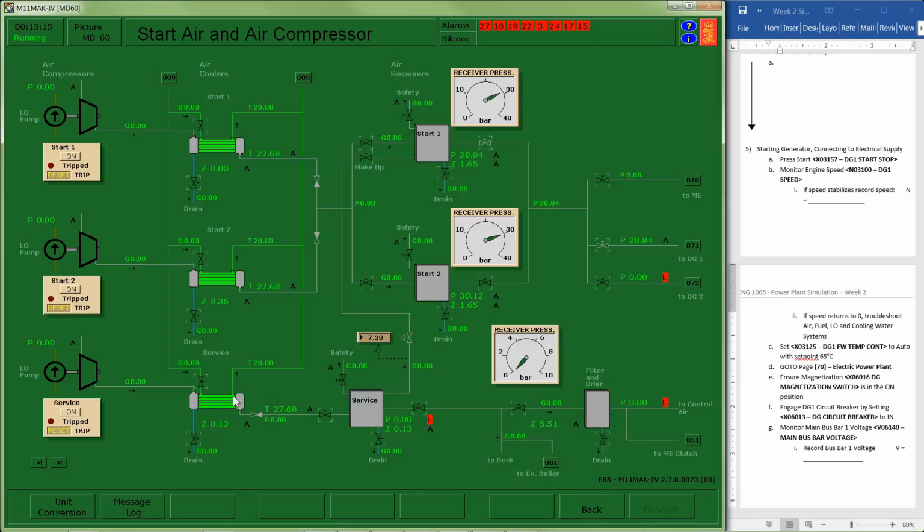Okay, so we're back to the simulation. What we want to do is get our systems up and operational. So I'm going to open up my water valve here, and we can take a second to see, is that actually doing its function? I open up that valve, and I'm going to monitor my flows. Even though I opened up that valve, I have no flow. Tells me that I have a problem.